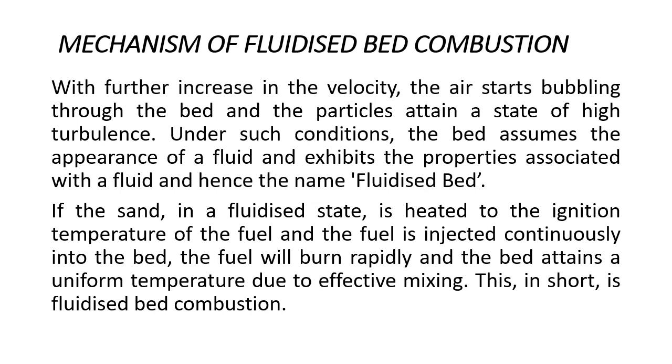If the sand in a fluidized bed is heated to the ignition temperature of the fuel and the fuel is injected continuously into the bed, the fuel will burn rapidly and the bed attains a uniform temperature due to effective mixing. This in short is fluidized bed combustion.